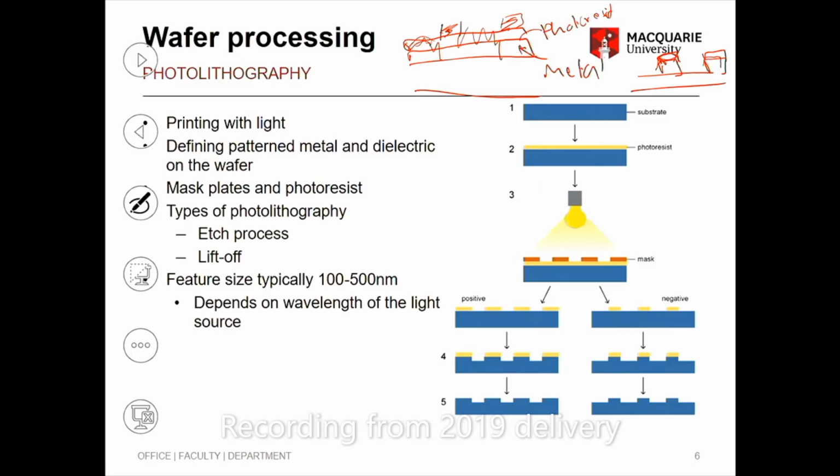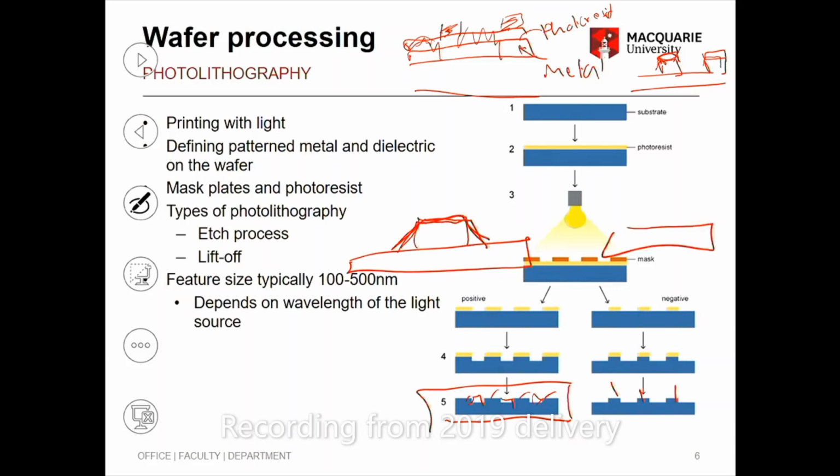So in this method, you put the mask, opening up your tracks, and then flushing away the rest. So if you do positive etching, you get, say this is metal. These are your tracks. If you do negative etching, you will have tracks in these places. Now, you won't have perfect tracks, so it won't be exactly square shaped. They can have a positive slope. On your substrate, your metal track can have a positive slope, or your metal track can have a negative slope.